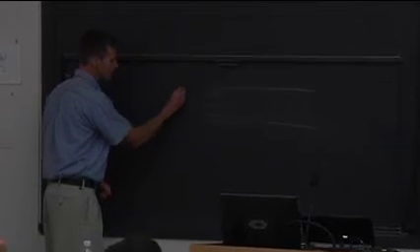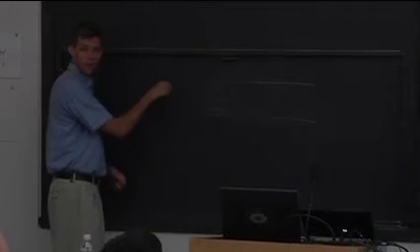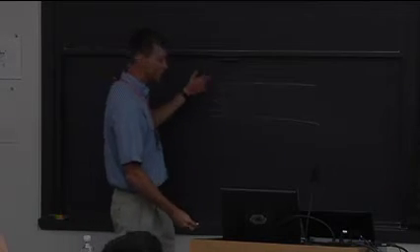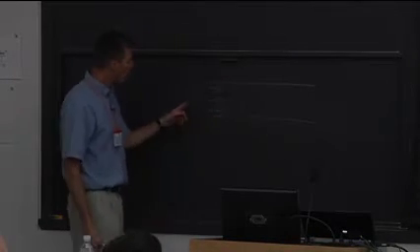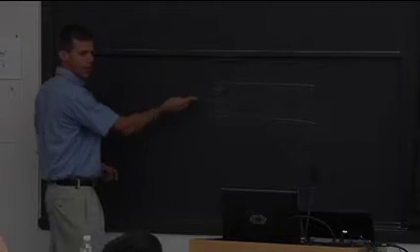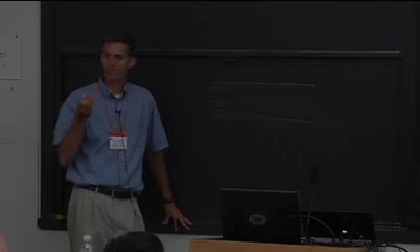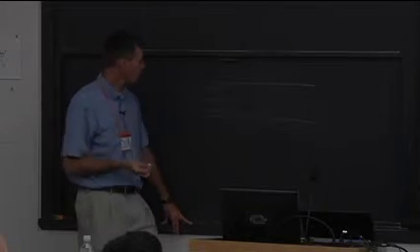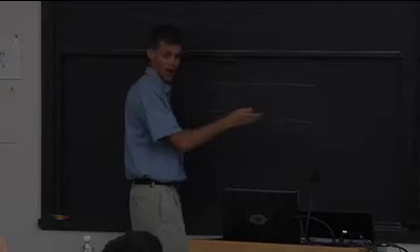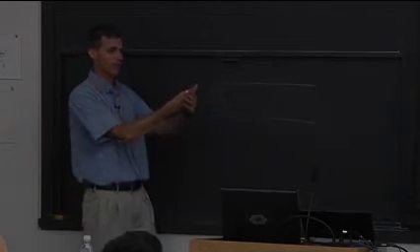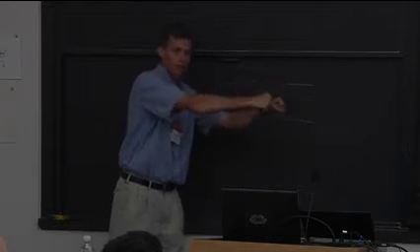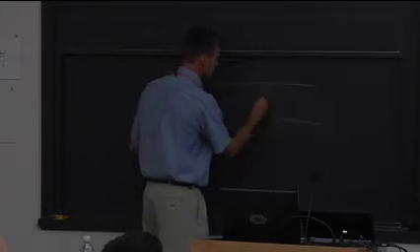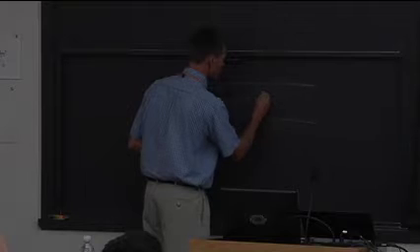Now let's say I add some spin, some swirl to the flow. All right? Well, no problem. It just introduces an azimuthal component to the velocity. But once the ratio of azimuthal momentum to axial momentum starts to get on the order of 1, so when the flow is spinning, going in the azimuthal direction just as much as in the axial direction, you get a phenomenon called vortex breakdown, where the flow all of a sudden will do this crazy thing where it will stop. It's moving 100 meters per second, just blasting through the pipe, and it's like it runs into a brick wall. It stops, and you get this bubble which time averaged might look something like this.